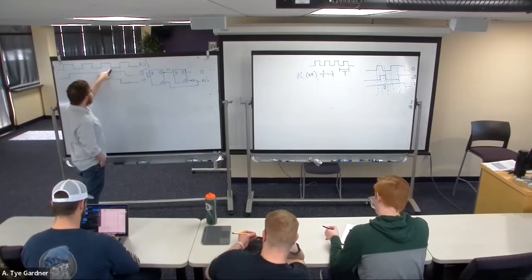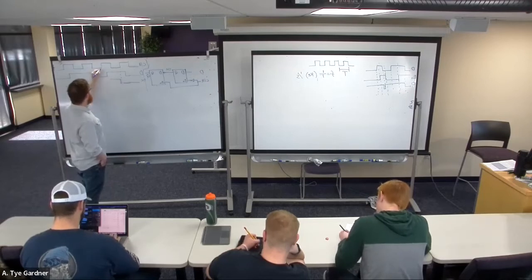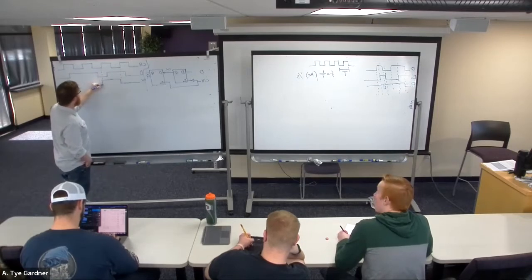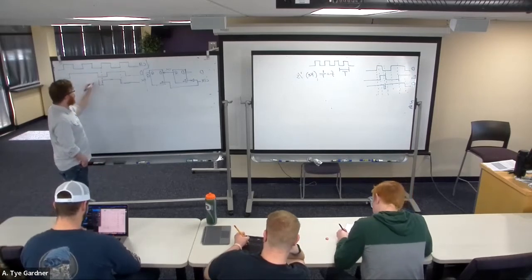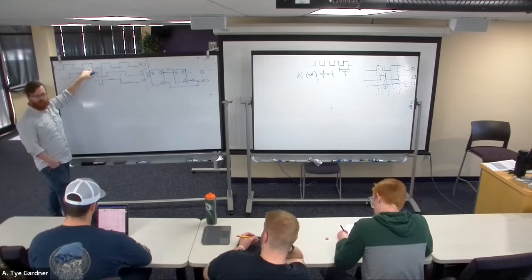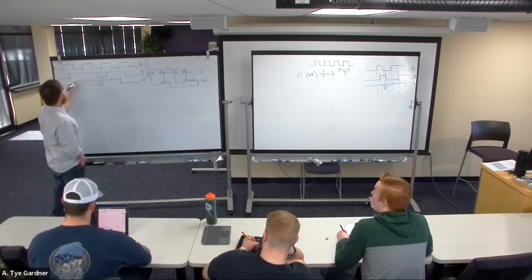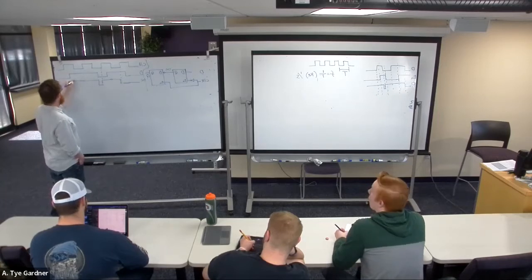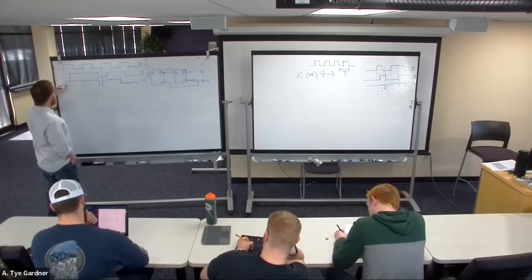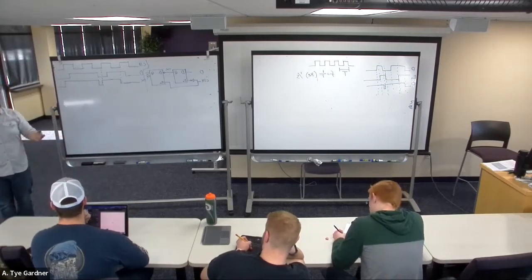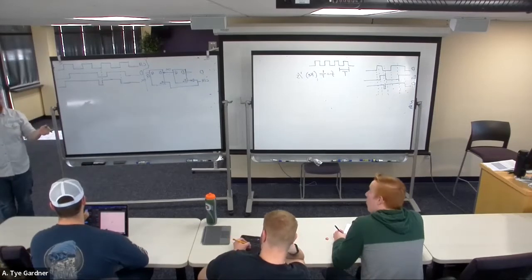Follows D, clock goes high, nothing can happen until we turn back on our enable. D goes to 0, D goes back to 1. Here, where we turn off the circuit again, turn off the enable, it's frozen at 1. Here, we turn it back on, still 1, turn it off, still 1. Here, you can follow. Okay, so that's alpha. I'm just looking at, is it enabled or not?